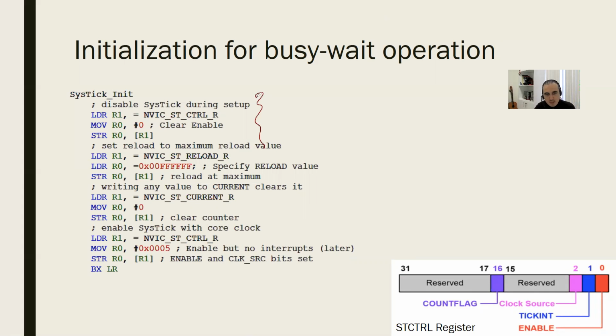Guys, this part was to make this bit 0 so that it is connected to the AND gate, which was also connected to the clock. The counter will be frozen. So while I'm initializing it, I want that device to stop. That's what I do. I disable it by ANDing the clock with a 0, that 0 being this enable bit.